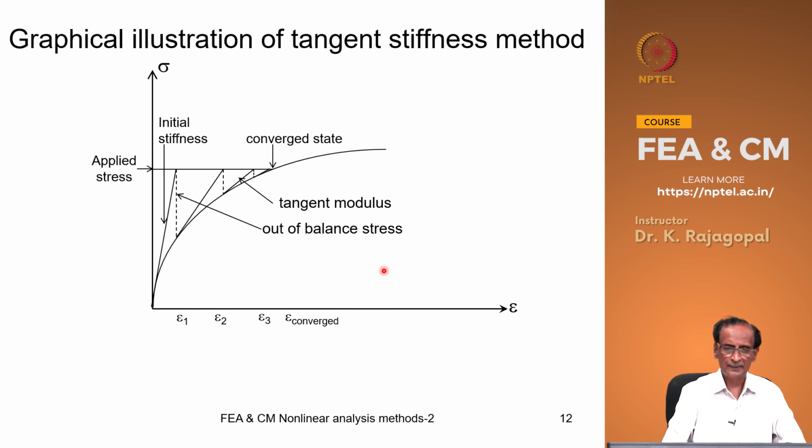And then the other one is the tangent stiffness method, where at every stage we calculate the tangent stiffness and estimate our new strain increments.